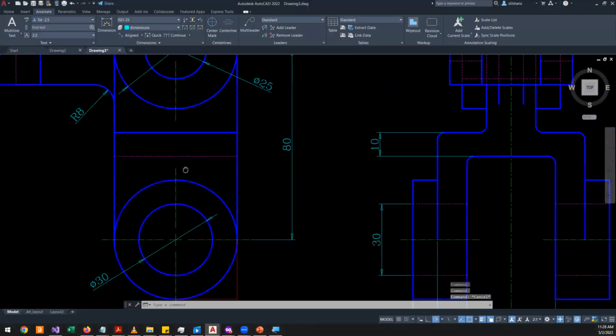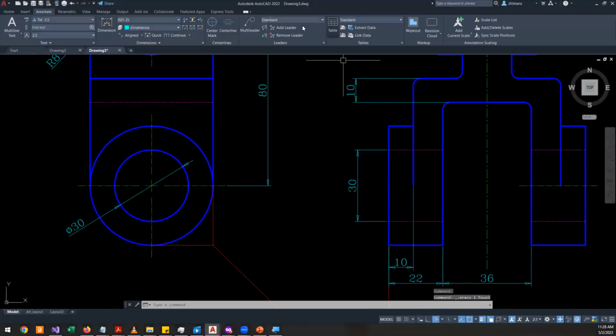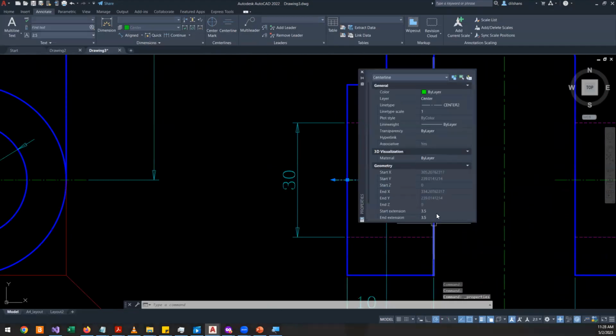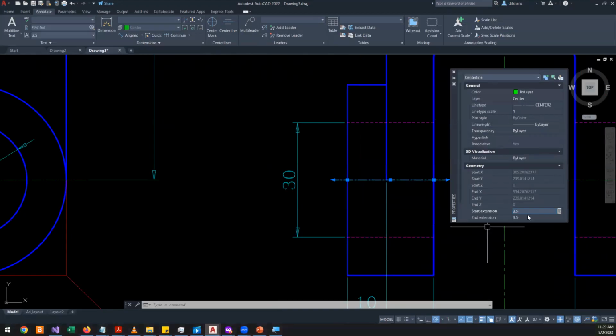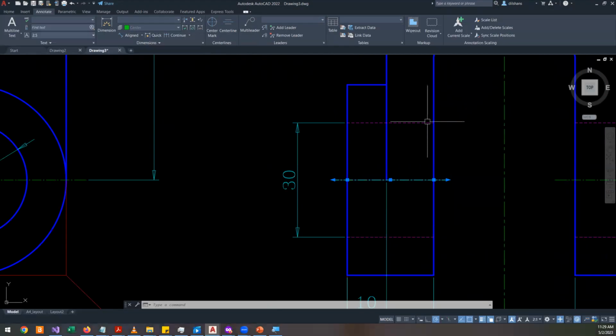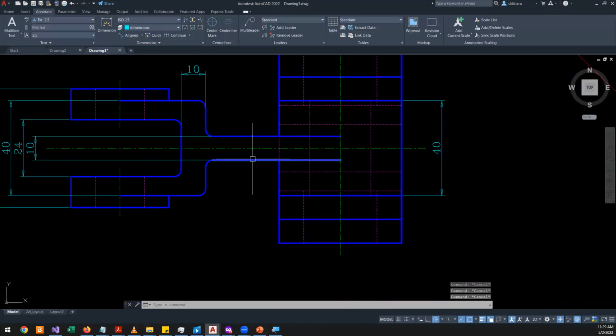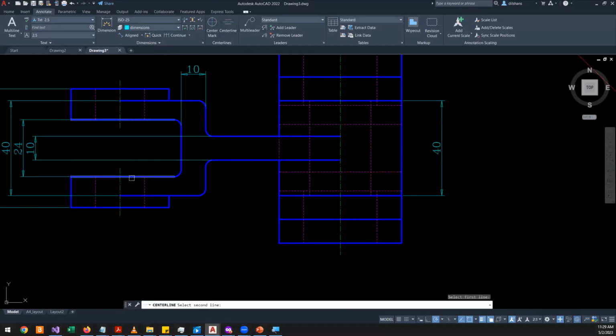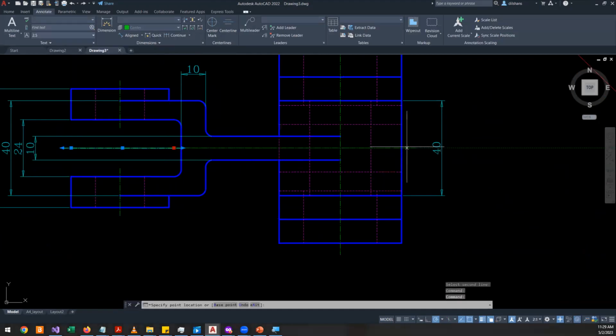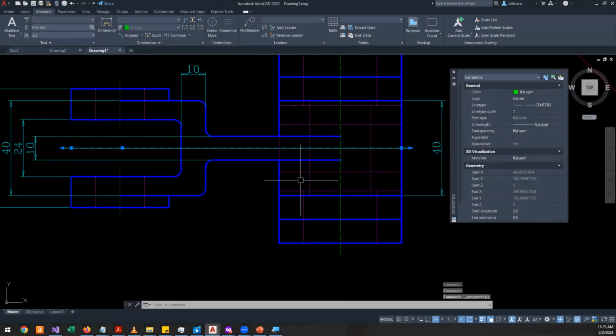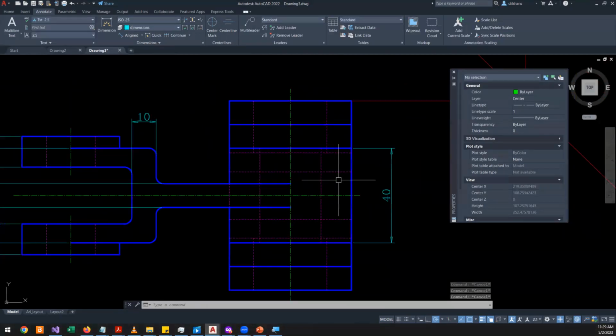And similarly, we have this command to define the axis, like here, and it also has controls. You can control the extension of that axis. This will make your life much easier than drawing the center line manually. So in this case, you can put the center line here, then move this grip up to here, and then modify whatever the length. As I mentioned before, this is a somewhat difficult drawing.